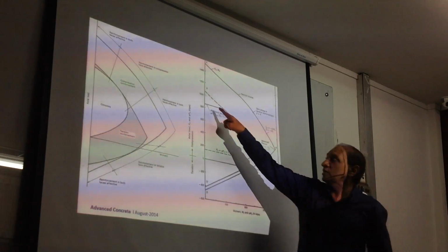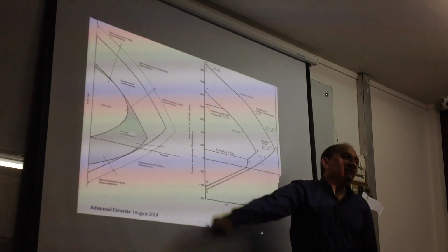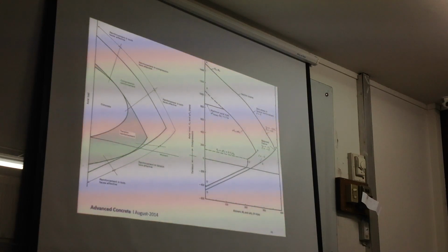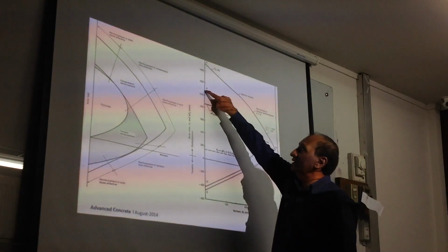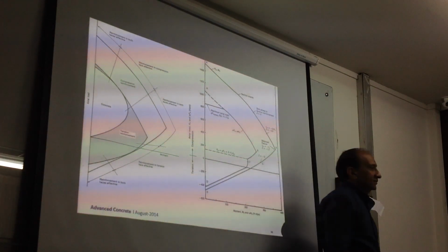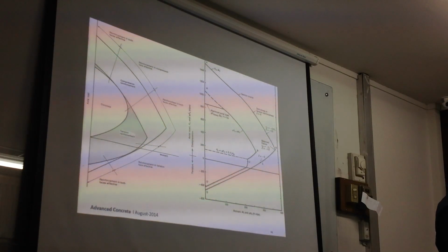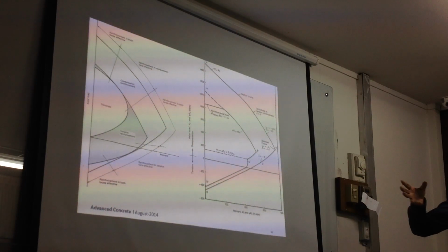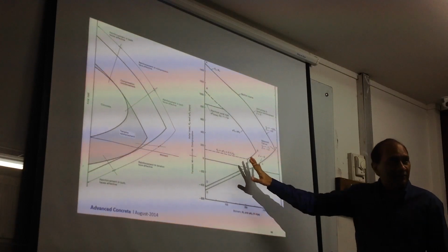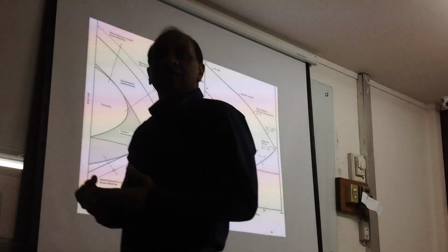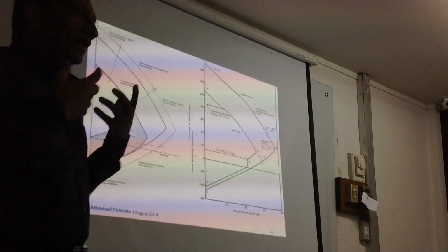That is a cutoff line that you draw, an artificial cutoff to prevent compression failure, brittle failure. So even though the capacity calculated is like this, ACI will apply another factor of 0.85 and cut it there, right? Because they don't want you to go too close to pure compression. So all these things we can see from these curves. They are very, very rich information and a lot of things that we can extract if we understand how to use this curve.